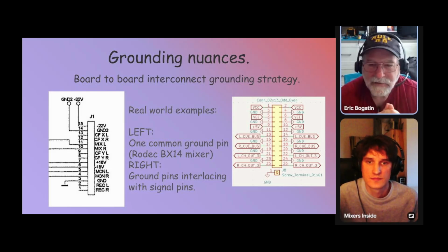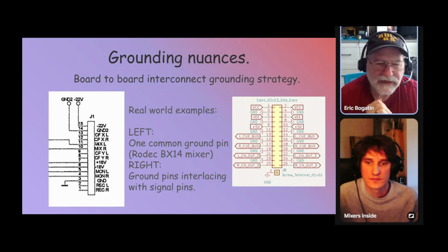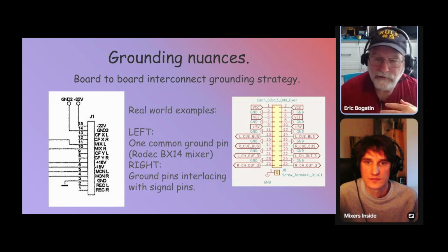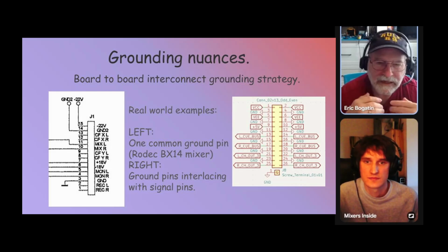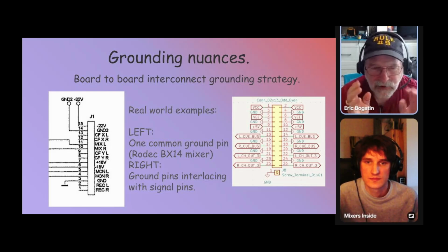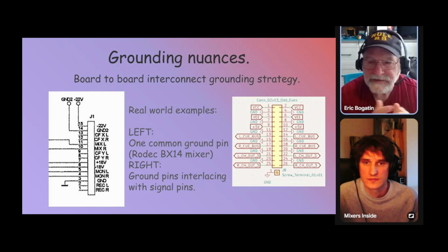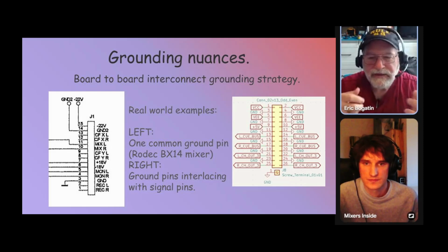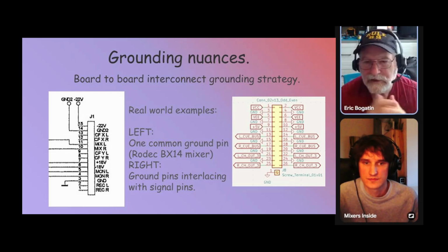I did a webinar a couple of months ago where I used that as the example, and I showed the crosstalk that we get in the ribbon cable coming off of that connector. It's all about, you don't think ground, think return path, like you said, that you want to keep the signal and return close together to minimize the loop inductance and to minimize the magnetic fields that come off of it and couple into other loops.